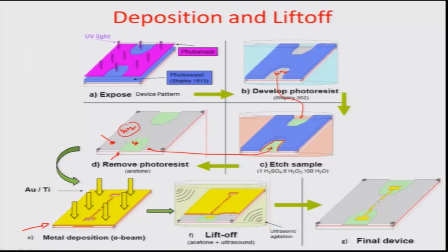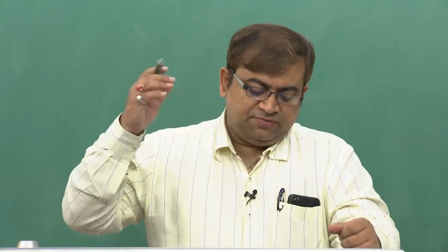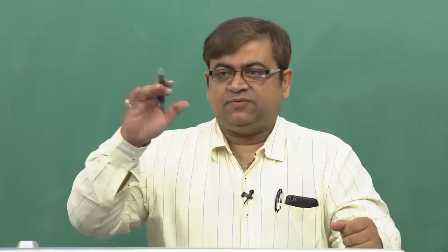I can use this for a different alternate protocol, where I can again make a sputtered film, again make a photolithographed film or a resist film on the top with another set of lithography, where it removes these regions typically, and then deposit metal, which can be deposited by a variety of ways and means, which we will cover in a little bit later topic. One of them is called thermal evaporation, another is called sputtering. So there is a deposition of a metal vapor typically, whether it's in plasma form or it's in passive form, on the top of a wafer.